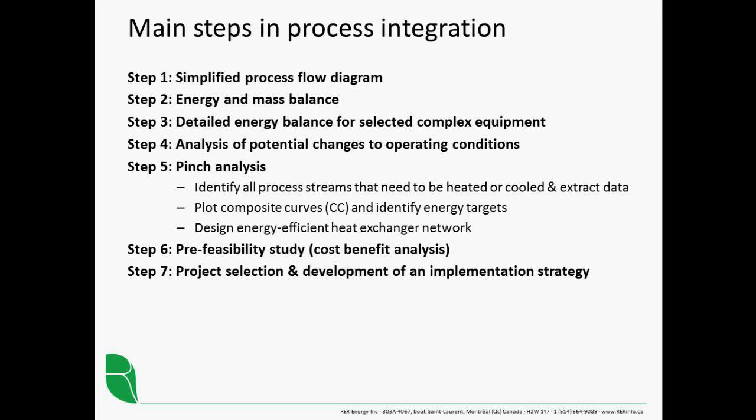And we may observe there that there are certain particularly complex or energy-intensive equipment that we'll need to perform a detailed energy balance for. This, for instance, could be a dryer, where instead of just considering it as a box with energy going in and an initial and final temperature, we might actually look at the processes within it to identify the heat that's being required to raise the input air, to raise the temperature of the material to be dried, to evaporate the moisture from the material, to superheat the water vapor once it's been driven off.